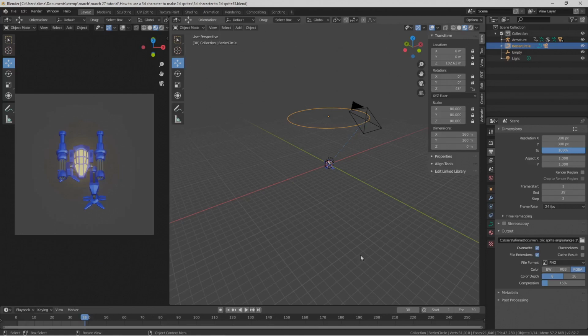Okay, just so you know what it is, the other render engine is Cycles. Cycles is when you want to render things with very accurate lighting. You get more effects in Cycles. The reason why you typically choose Eevee over Cycles is for rendering time.